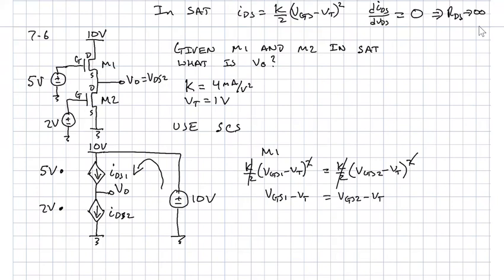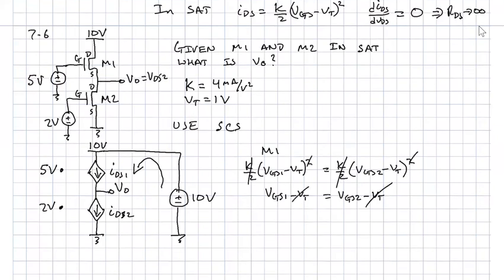And this one, if we just took a step back, that's the mathematical statement. But if we looked at it, we could say that from the information that we're given, K is the same for both of those transistors. That's why we're able to cancel it in the equation. So if K is the same, then for that transistor to produce the same amount of current, we would have to have the gate source voltage be greater than VT by the same amount for both of those transistors to give us the same value of, again, drain source current. So this relationship has to hold. Thresholds are the same, so now we can cancel those. And we can say that, again, gate source voltage for number 1 has to be the same as gate source voltage for number 2.